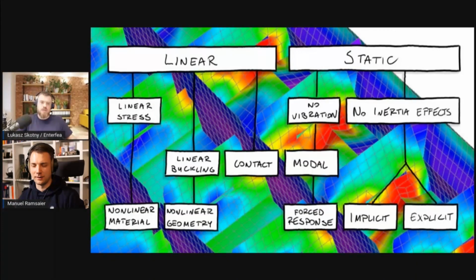But with the implicit thing, time has no physical meaning in this case, right? So you have just your load application. In implicit, I would say it does have. But I could have something looking like implicit analysis, but with time that doesn't have any physical meaning. It's just dummy time. It's a way for the solver to know what load should be applied at which situation. Yeah. Let's say not moment, right?